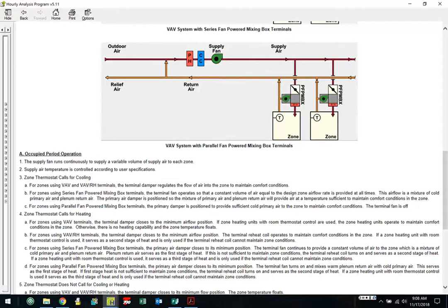So what happens here is this fan is going to be producing colder air, 55 degrees, sometimes a little bit warmer than that, but usually not too much. It goes through the supply ductwork and comes into a variable air volume box. The zoning, which we've established in an assignment, we'll put in the same number of zones that we used for the VVT or the VRF system. So the zoning will remain the same.